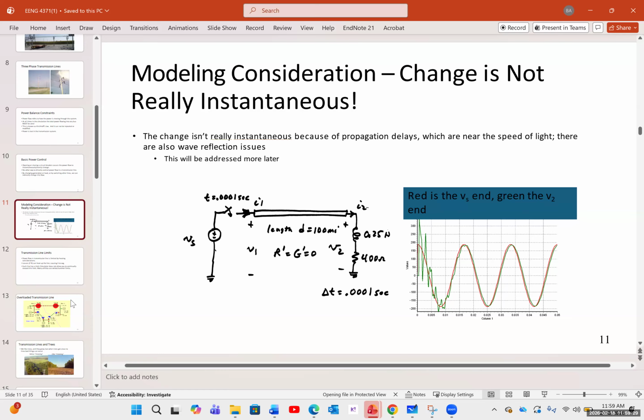That's a good question, but there's a limit on the amount of power that bus 2 can supply. So another way is actually to redirect energy. Instead of going through this transmission line, bus 2 can send the power to bus 3, and then bus 3 to bus 1. So you can redirect power. That's the reason we have multiple transmission lines between states, so you can redirect power through another line. And that's one of the benefits of having these mesh networks in a power system.